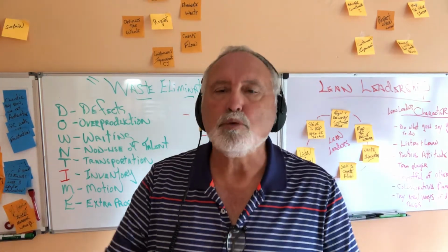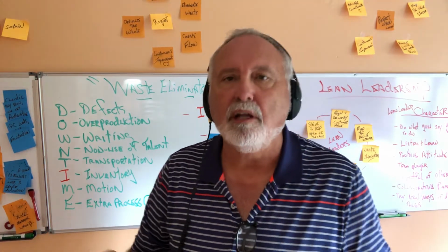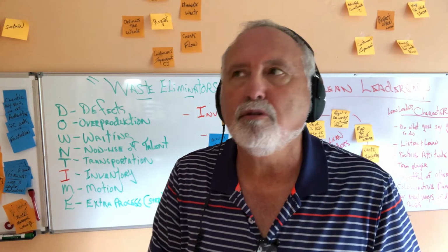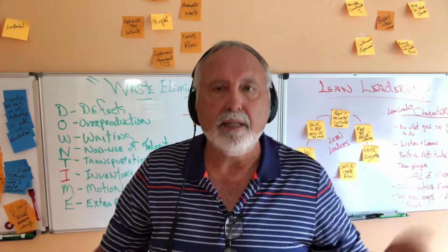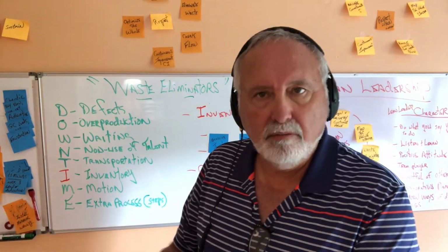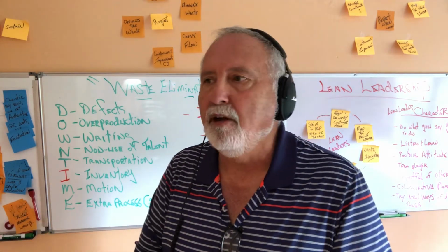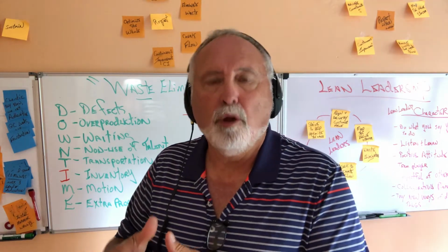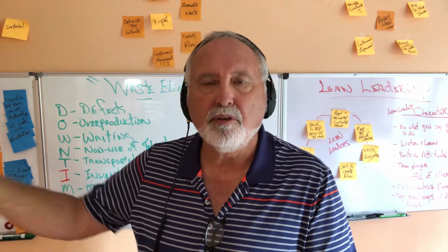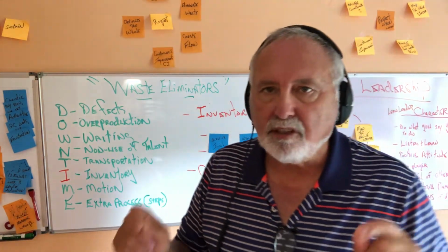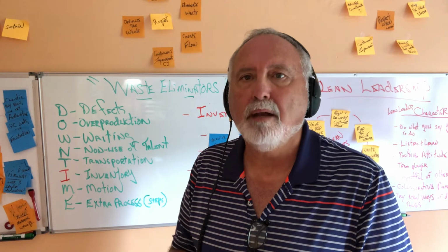Notice that these wastes, it's very rare that I have one waste occurring. They all intertwine on a site that has a lot of things happening, so you've got to be watching for all of it. If I can reduce inventory, that's something I don't need to manage. It's just showing up on a well-planned schedule, just in time. It generally shows up Friday, and I have enough material to get the work I need to do next week done, Monday, Tuesday, Wednesday, Friday, right? So that's a good plan. That's a tight plan. That's what we're looking for. We don't want excessive inventory. That is a waste, and it causes a lot of problems on job sites.